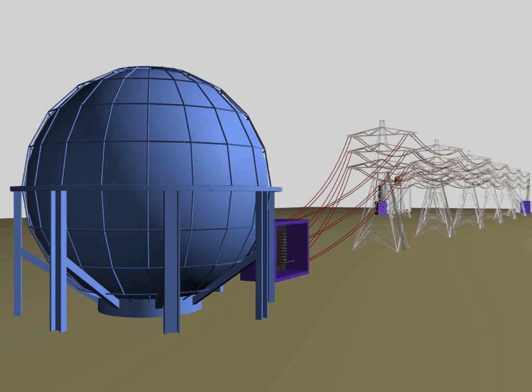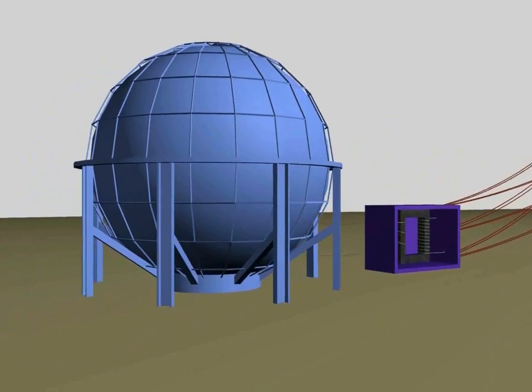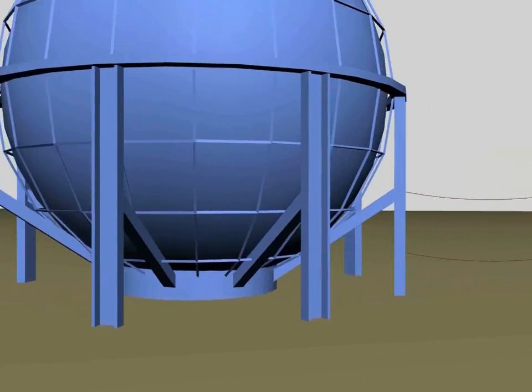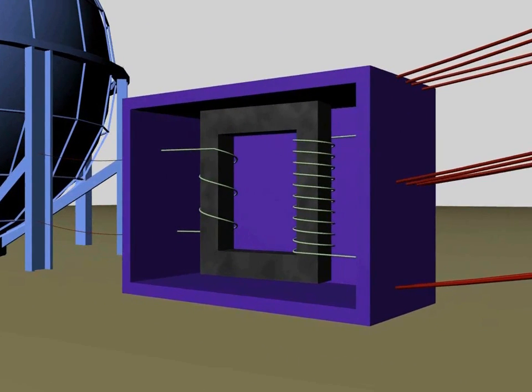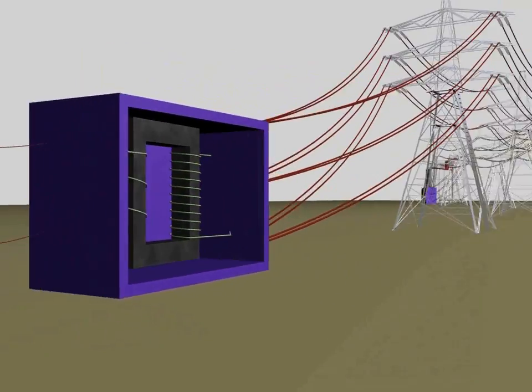The national grid is the network of transmission cables and other components that help deliver electricity to homes. Starting from a power station that generates electricity, there must be a step-up transformer to increase the voltage and decrease the current. In fact, we do not need the high voltage, but we really need the low current.